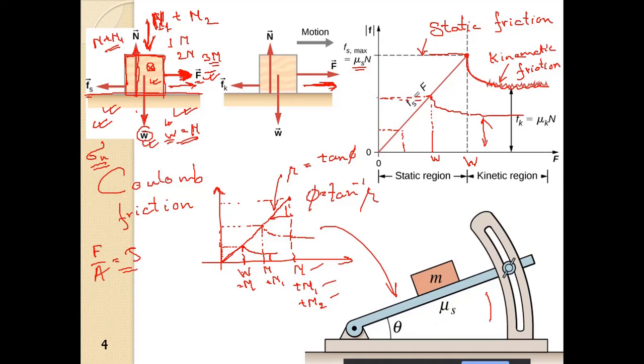If we go on increasing this angle, then at a particular angle, this mass will slide over this board. This mass and this board have a friction, that is the mu s. The angle theta at which it will start sliding is equal to the angle of internal friction phi, almost approximately equal. Some differences may be there.